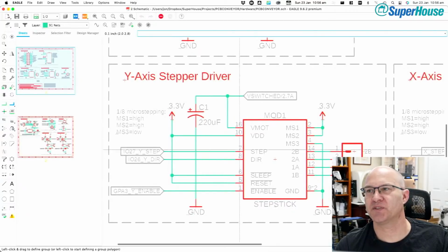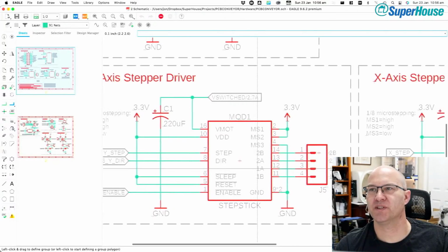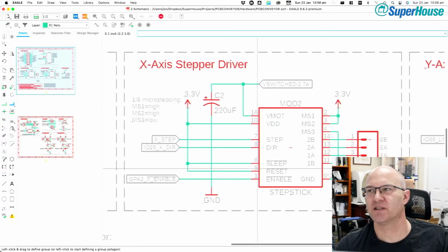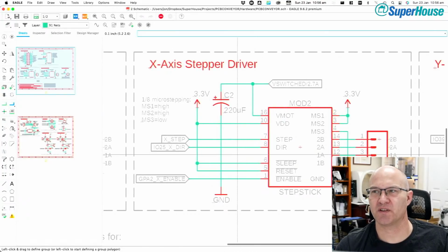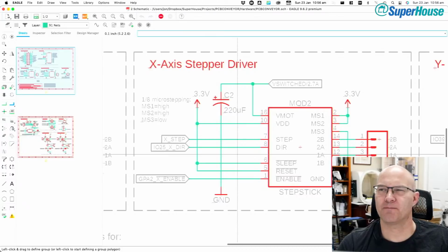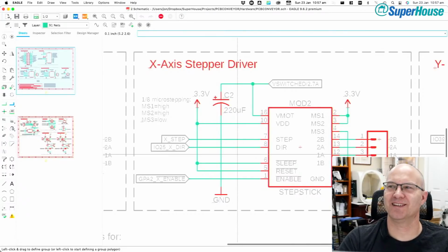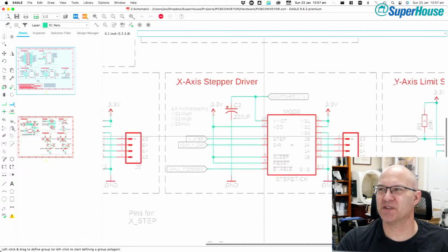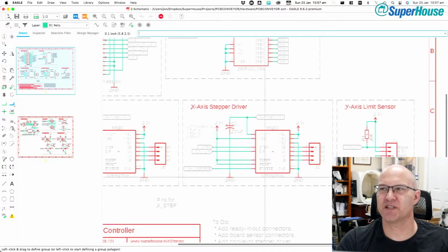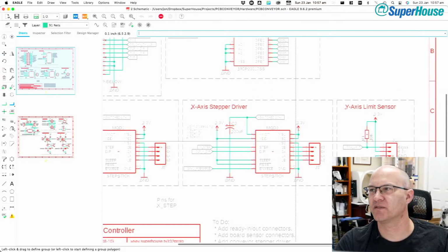But what I've done is put down the footprints for 2 of these stepper motor drivers. So you can go old school and put something like an Allegro A4988 or whatever it is. Is that the part number? Whatever. Yeah, one of those little modules on there. These are the modules that are typically used in things like 3D printer controllers.